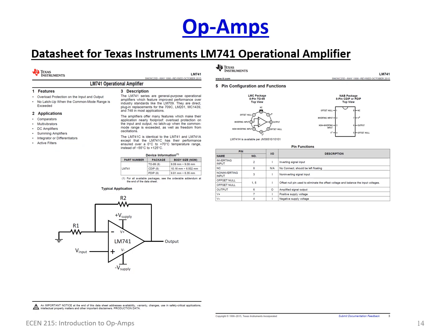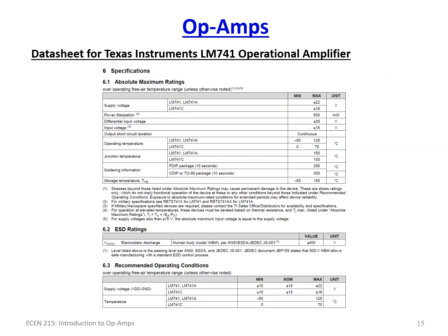And of course the pin out of the package, which we were just looking at a moment ago, blown up. So you have that. And of course, one of the things you always got to pay attention to when you're looking at real devices is voltage limitations. There are supply voltage limitations. For this particular model of op amp, the LM741A and 741, you're limited to plus or minus 22 volts.